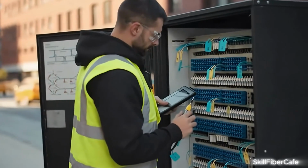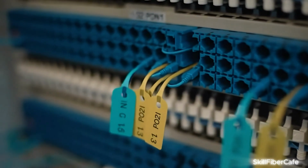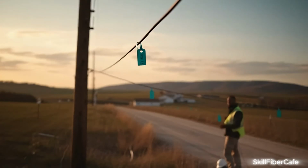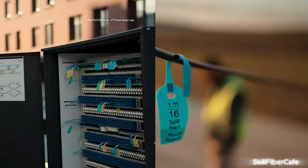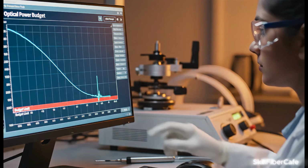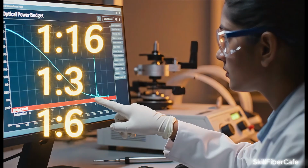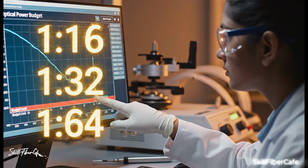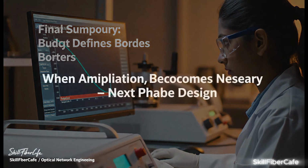Urban FTTH networks often balance 1:32 splits with 10 to 15 kilometers of reach. Rural networks prefer a 1:16 split to ensure strong margins across longer routes. It's always a trade-off between coverage and reliability. The optical power budget defines performance borders and makes split ratio decisions possible. It tells engineers how far light can travel and when amplification becomes necessary.